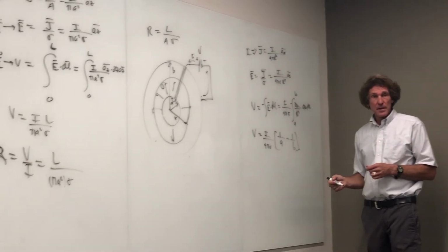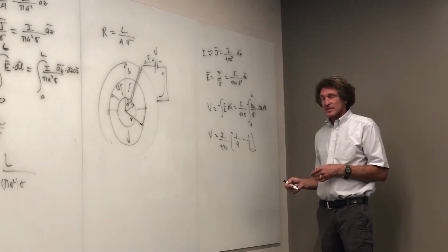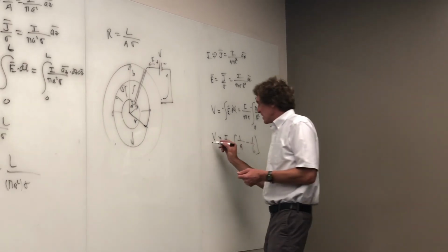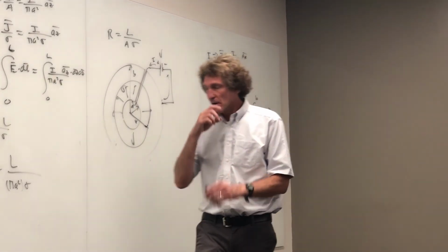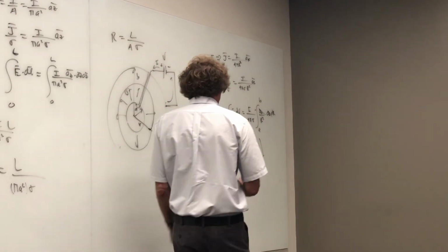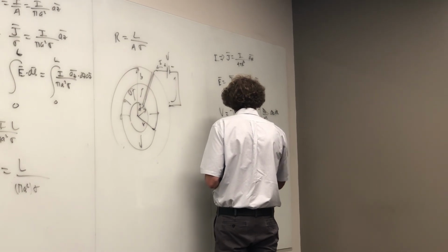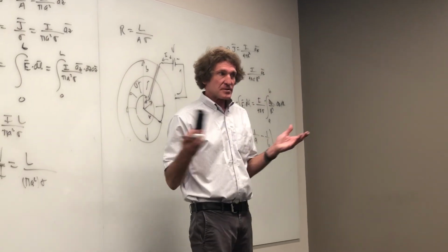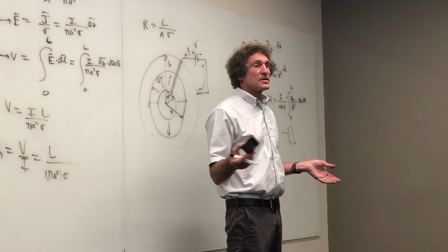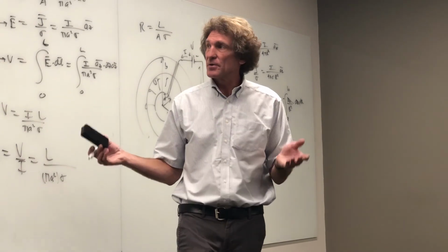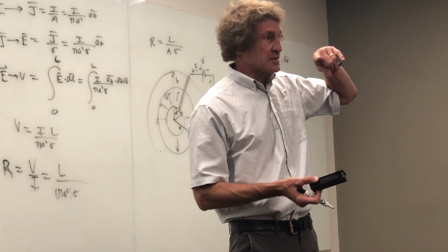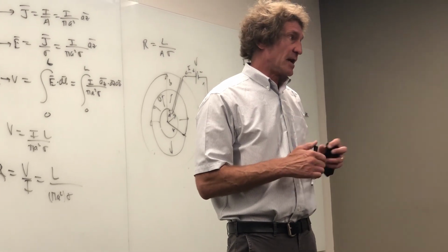Do you follow me? Now, if that's the voltage, what's the resistance? Just divide this by I, right? And if I divide that by I, you can see that in fact, it's this. So that's another way to get resistance, now for concentric spheres. Obviously, the concentric cylinders, you could use that too, couldn't you, class? I could have an inner radius A, outer radius B for a certain height cylinder, calculate resistance between that, okay?